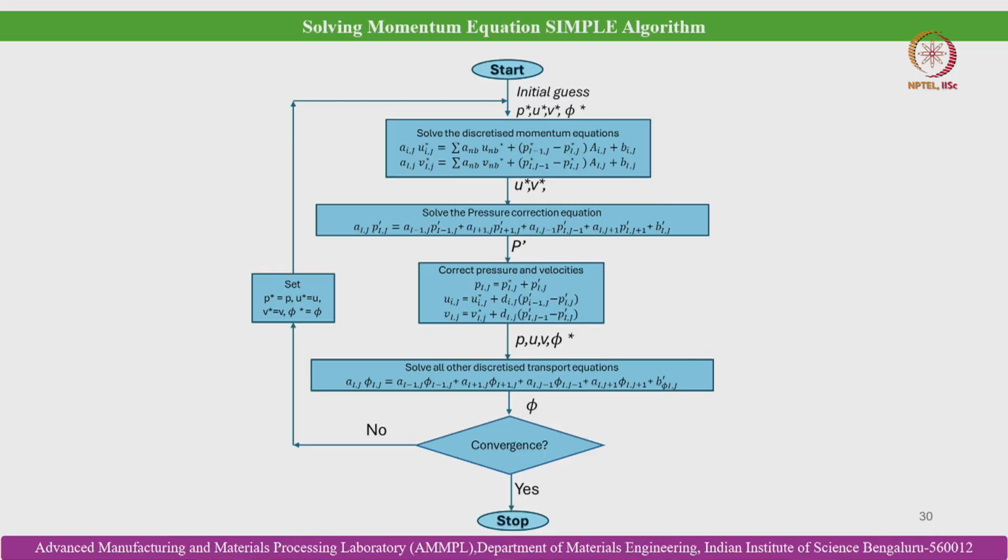So, we have discussed how the discretization schemes are employed to discretize a domain, and thereby we can solve the governing equation to estimate the temperature and flow parameters in the case of coupled heat and mass transfer and fluid flow problems. So, let us start with the SIMPLE algorithm, which stands for the semi implicit method for pressure linked equations.